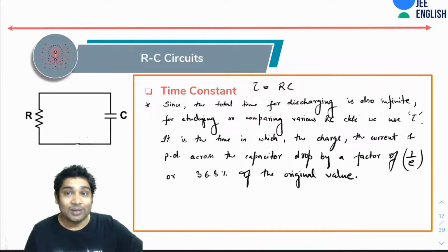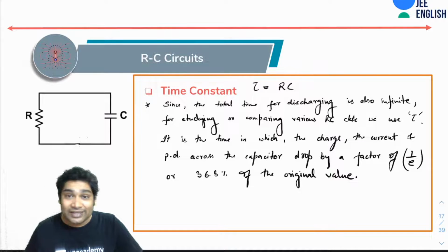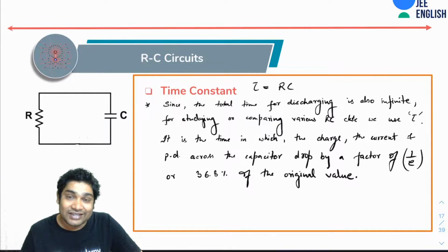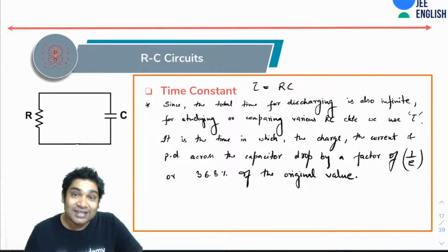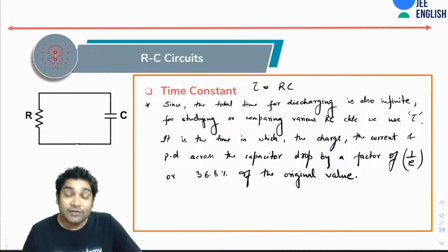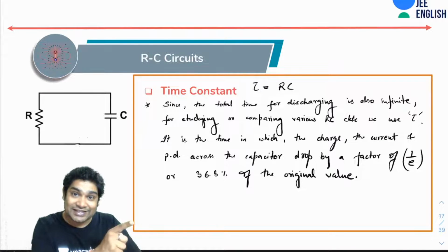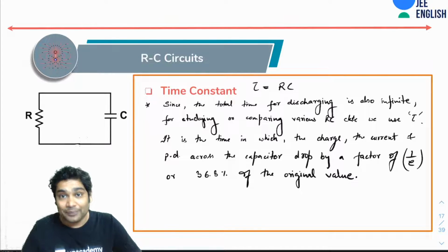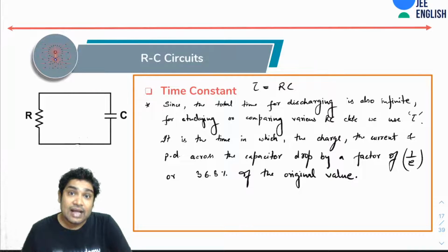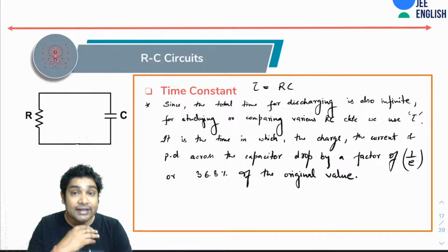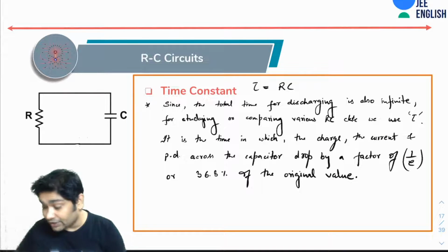Similarly here, we are using the concept of time constant. We are just using a different term, where in the mathematical equations everything is falling by 1 by E. So after one time constant, if I started with a charge capital Q, the charge would become 36.8% of Q, and after another time constant it will become 36.8% of this charge, so it would be 0.368 squared times Q, and so on. Now these time constants help us compare these circuits. Why? Because practically I would assume that the discharging is complete after 5 time constants.